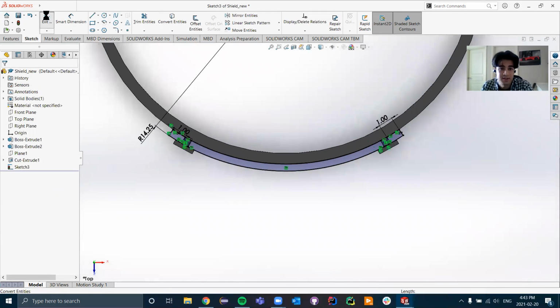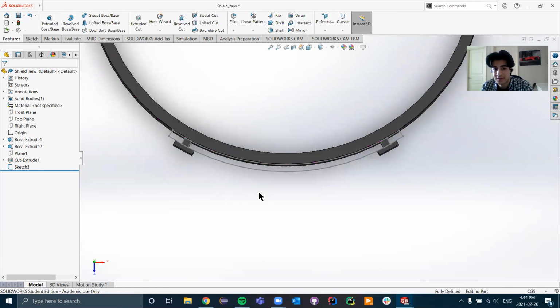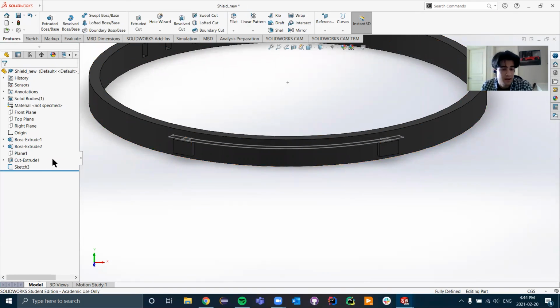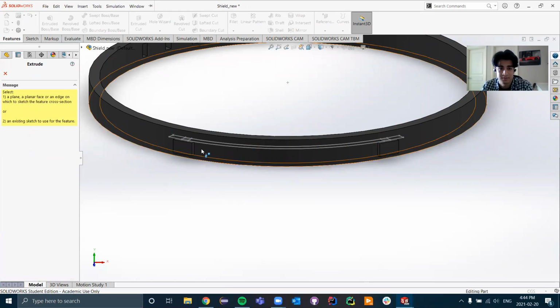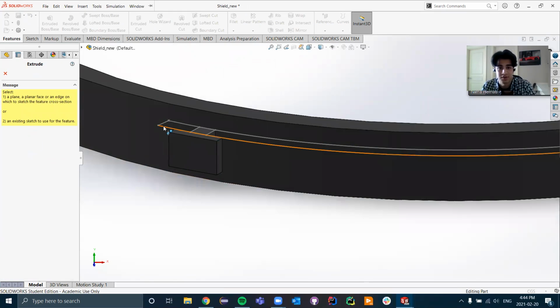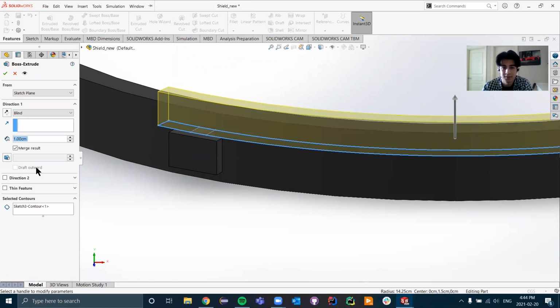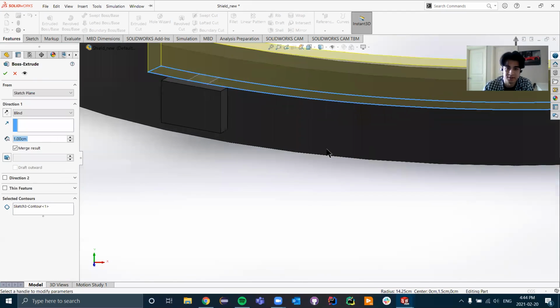And then if we actually exit our sketch, the nice thing about this is we can do multiple extrusions at once. Now, okay, let's see. Presently, I think we can also get rid of our other objects as well. But let's keep them for now. I'm going to extrude this. So essentially, we'll take this contour, give it a moment, nice. And it automatically selected the largest contour, which is what we want initially.